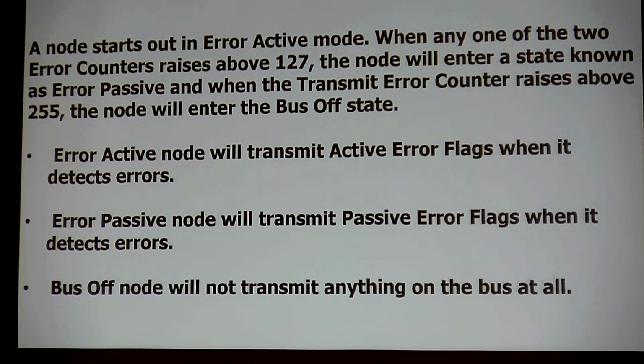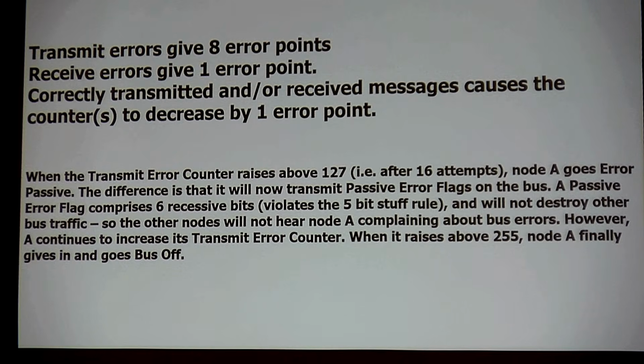And then once I go to error passive, that's over 127, and at 256, I get kicked off the bus, and that's permanent. You cannot get back on the bus once you're kicked off. I'll show you how you get back on.